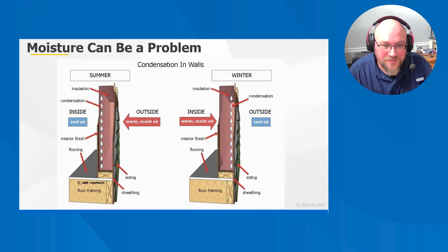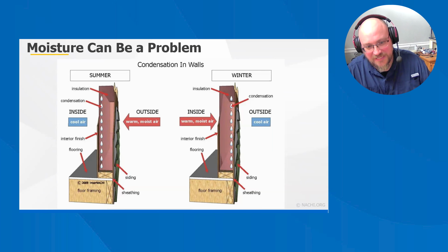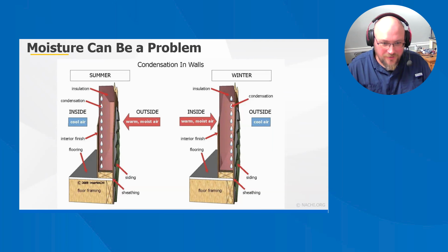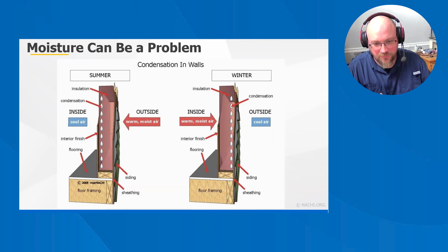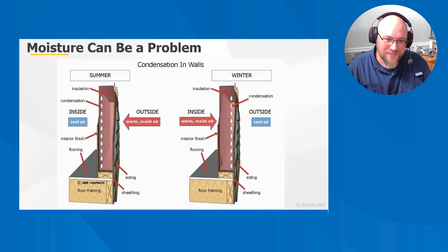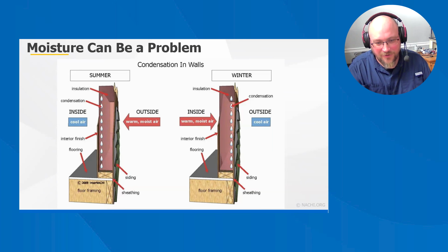Unfortunately, the only other thing you could try to do was they were going to take the baseboard off and run a bead of caulk, and try to seal the sill plate to the concrete. But all that's going to do is push that cold surface inside that wall instead of it coming out to the baseboard.